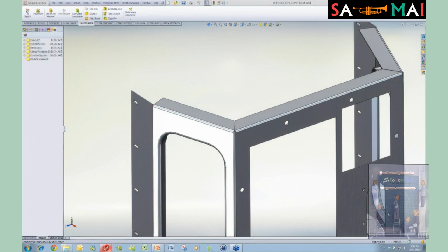We've got one more. Maybe take the weld length to some edge. I'm not understanding your question. Take the weld length to some edge. Like if you knew what that edge length was, if you click on any edge inside of SOLIDWORKS, in the bottom right you can tell what the length of it is. It's going to kind of do the measure tool for you. So if I know, all right, well that's 59 millimeters long, I could come in here and modify that weld. I could edit it. I could add that into my template if I wanted to.